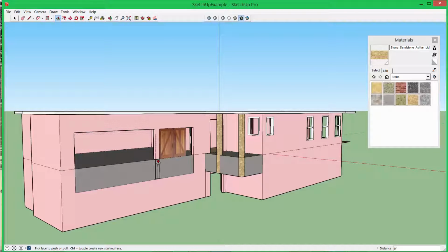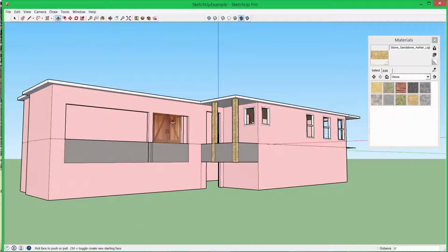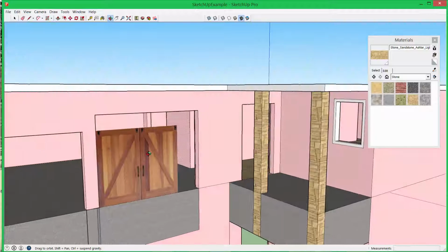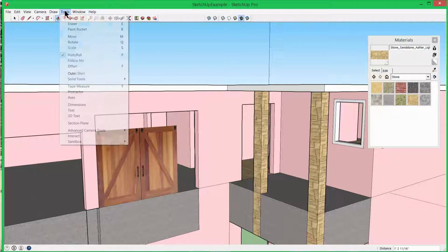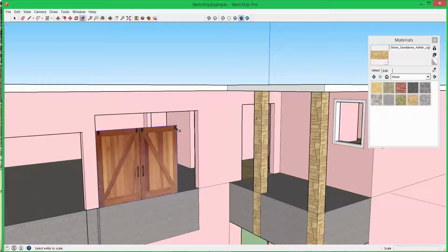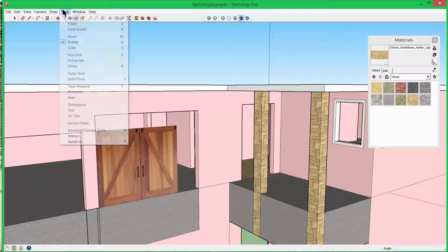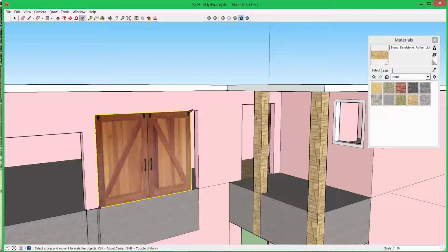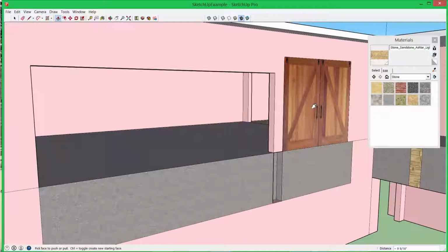Now you can see my door openings are rather large. It might be that it's out of scale, and so you'll do a combination of a few things. One is maybe the door is taller. And again, nobody's going to measure this. So a lot of the stuff I'm doing visually and not going crazy with. So I'm going to go Tools, Scale Tool, not rotate, scale, get my door, scale it up to a scale I want, and then you could fit the opening to the door itself.